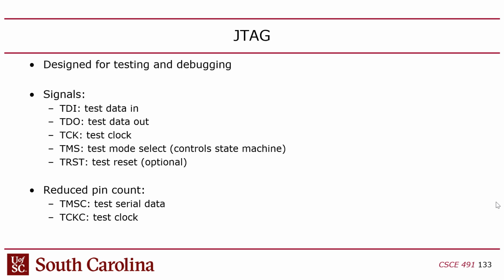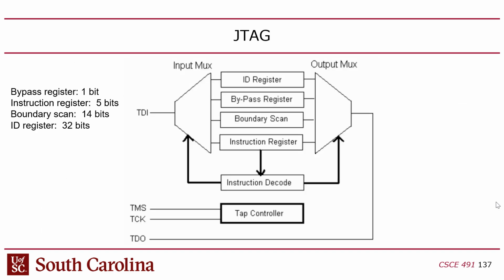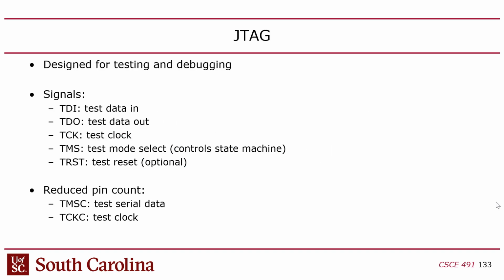So the last protocol that we cover is JTAG. JTAG is the way in which the FPGAs are programmed. It was originally designed for something called boundary scan. I have a history of that. No, I don't. So JTAG is designed for testing chips.